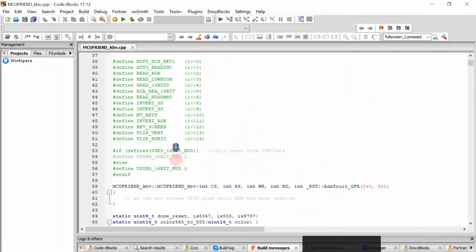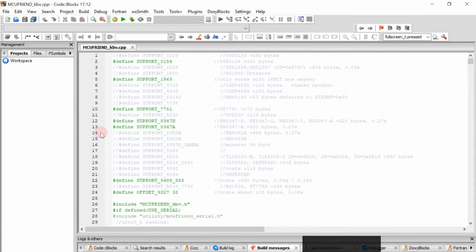When you find this number, just search for it in the library, and based on this there is one of those defines here that may be just commented. The reason they are commented is because this library writes the support for different screens, different monitors, to the Arduino, and it compiles the support for many screens and sends it to the Arduino.